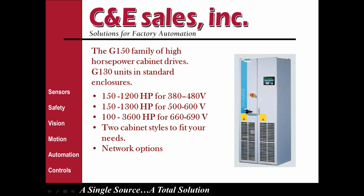The G150 family are G130 chassis units that are mounted in predefined enclosures. You can see there's much higher horsepower range, and that's because they can parallel the power modules from the G130s. They can parallel those and get much higher output with a pre-configured design.